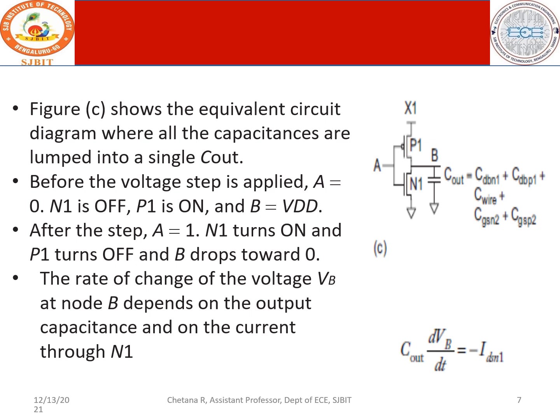Since this is off, whatever is the VDD, it has no path to go to the ground. Therefore, all the voltage, or VDD, is concentrated at this node, and this node is nothing but VB. Therefore, the voltage here is VDD. The voltage at B is VDD.